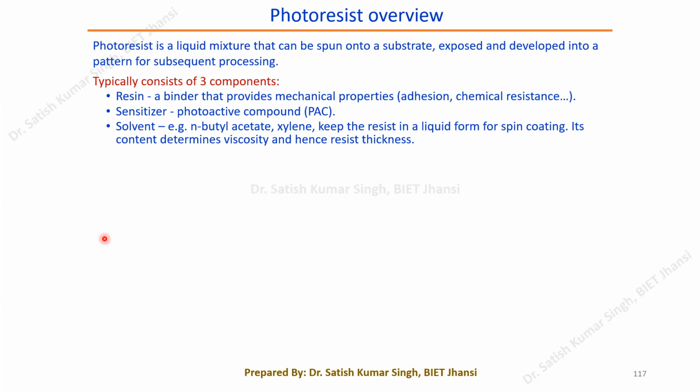Now today we have to look at the photoresist. Because, as we know, in the photolithography process we have a particular wafer, and onto that wafer we coat the photoresist layer, and that layer has to be exposed through a photo mask using UV rays. That way we are doing optical photolithography. So today's discussion is on the photoresist.